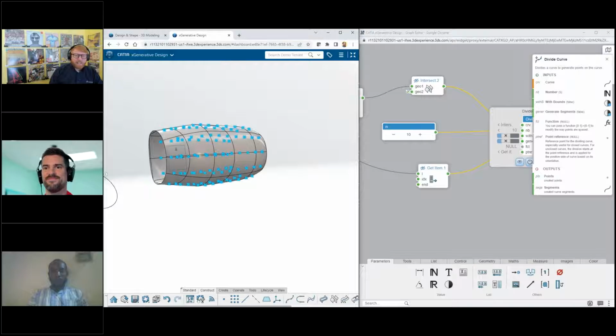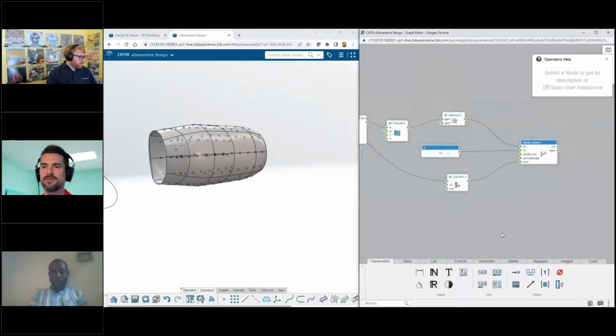I guess I'll try keep normal constant, whatever the heck that means, right? Yeah. And then you click on it and you go, oh, okay. It's just keeping all of the different sections of the sweep normal to the initial section, right? But what did those words mean in the beginning? Like, I don't know, right? I don't have a physics degree. I don't know what keep normal constant means, right? So yeah, over time, one of these little nodes has a help screen, like you showed, like the SolidWorks help kind of just flies out and explains things pretty well.